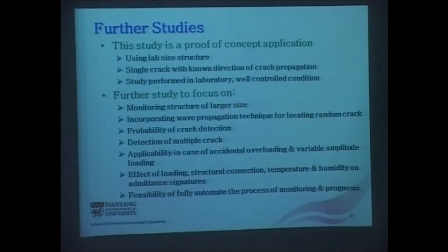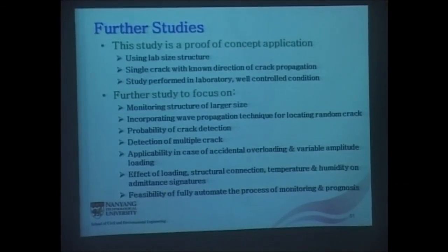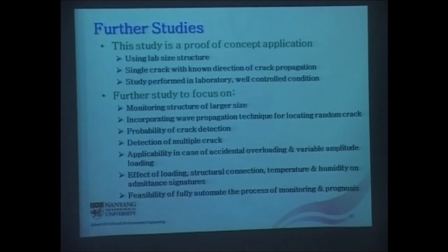Right? For a circular tube, it is a lot more complex because torsional waves come in. So we have a PhD student working on this circular tube because of the oil pipeline, in case there's a crack. And in an oil pipeline, when there's a crack, it actually propagates in the long direction because the hoop stress is double the longitudinal stress. So when it bursts, it goes in the wrong direction. I think 20 years ago there was a pipeline in Texas. One crack split almost 20 miles and the fire went on for 20 miles. So how to address these problems? We have a student working on that. Because of the torsional stress, it's a different set of problems altogether.